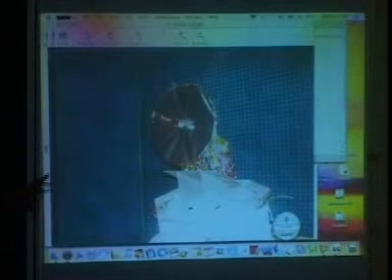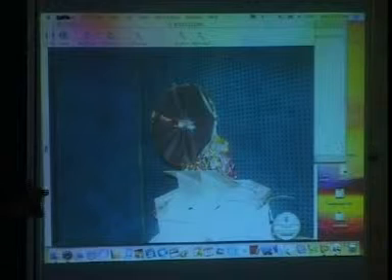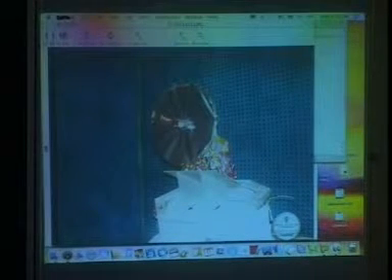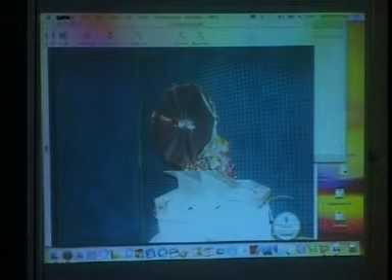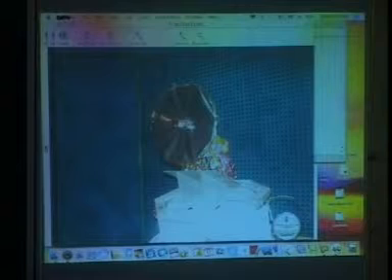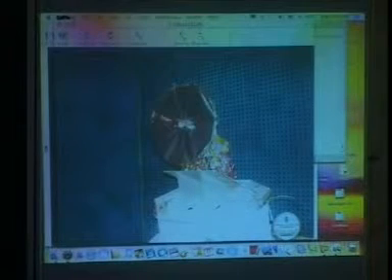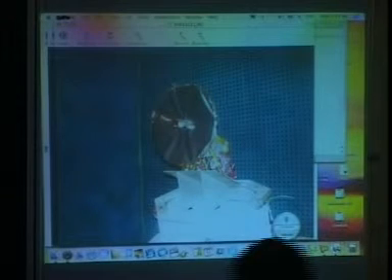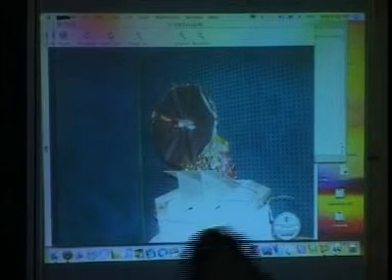And here in front, apart from that, there is another sheet, a special protective shield which is used. So this plus that together forms the total thermal design. This is apart from our mechanical and electrical design. There is a special thermal design. Otherwise, the antenna surface will get distorted and the beam will go off.